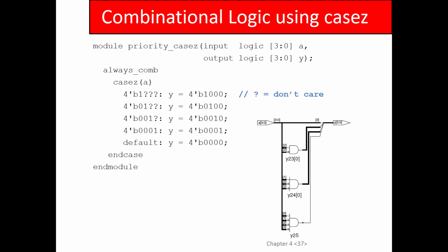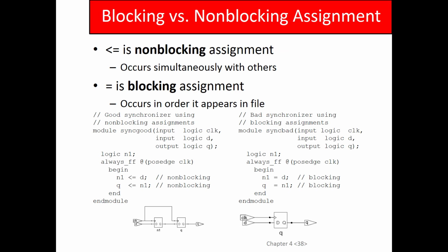Blocking and non-blocking assignment is kind of subtle. It's a subtle distinction. But the way to remember it is, in a non-blocking assignment, the assignment takes effect after all of the actions associated with a particular event have been evaluated.